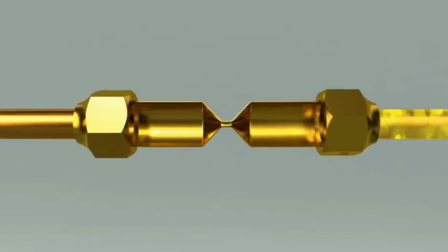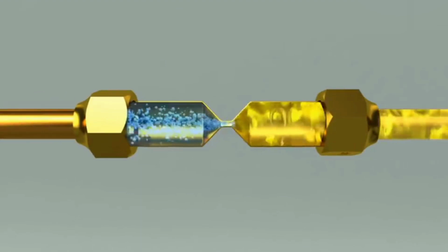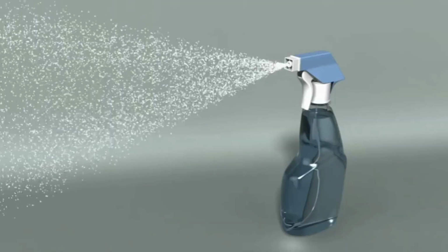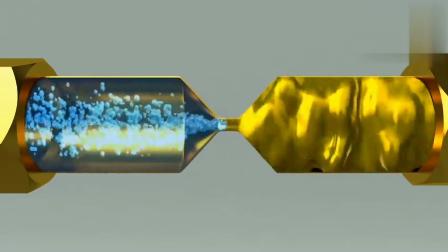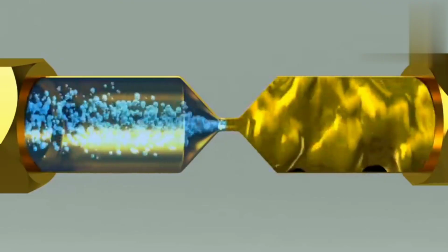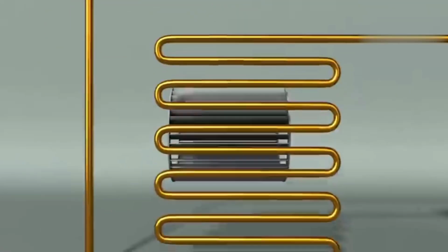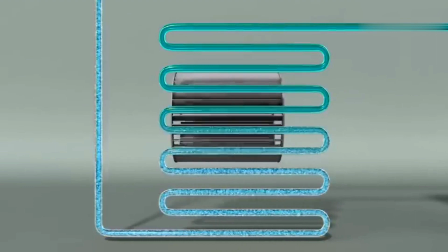There is a section in the expansion valve where the piping gets narrow, and as the refrigerant passes here, it splits up into many pieces. What we see here is similar to the principle behind water being spread from a spray. As the pressure on the refrigerant drops, its temperature drops dramatically as well. The refrigerant with lowered temperature then goes into an evaporator to steal away heat.